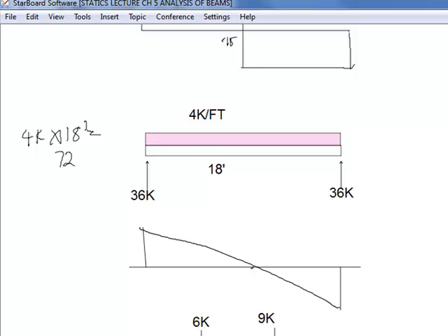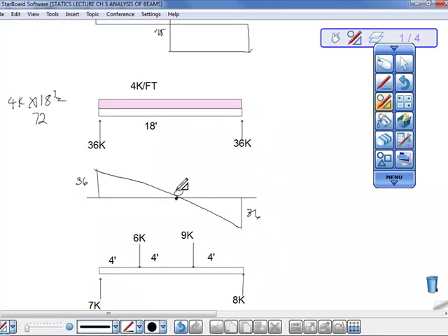That's your shear, and that's the moment where shear equals 0. That's not exactly drawn to scale, but so you go up 36 and down 36. That's your evenly distributed load, or your uniform load. That's what the shear diagram equals, and that's where the bending moment is going to be the greatest, and we'll go over that in a minute, is at where the shear equals 0. Does that make sense? That one was concentrated? Concentrated, you're right. Uniform, concentrated. Okay?